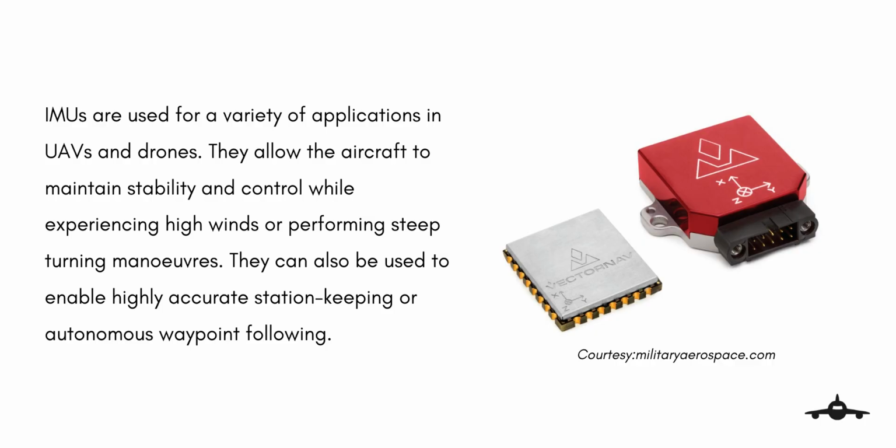It uses a combination of accelerometers and gyroscopes to accurately estimate the UAV's attitudes, including roll and pitch. It also uses magnetometers, a supplement to the accelerometer and gyroscope, to measure the heading, that is yaw, and to measure and report a drone's specific force, angular rate, and the magnetic field surrounding the drone.